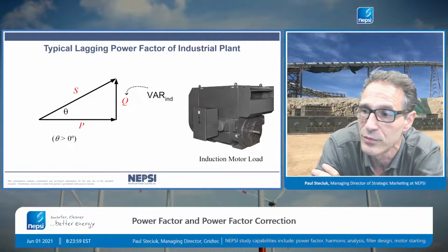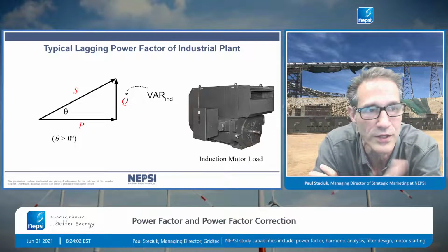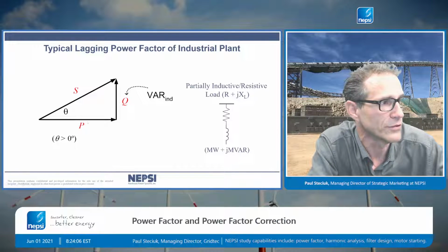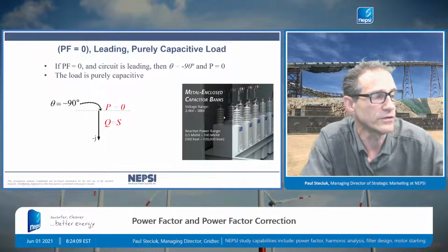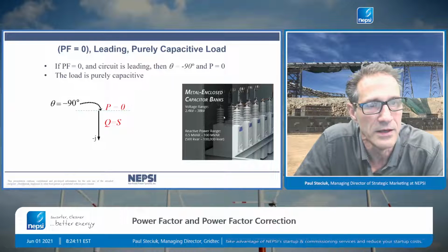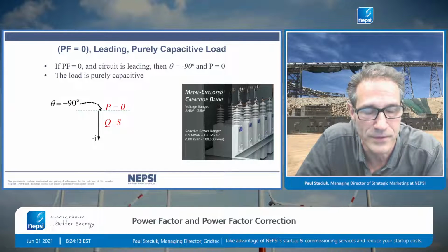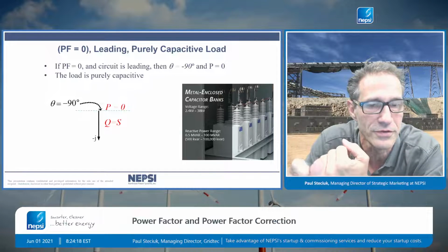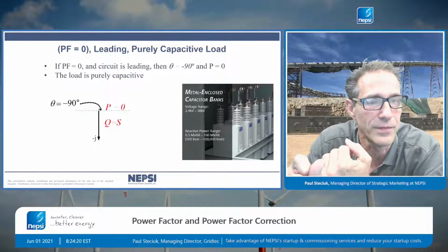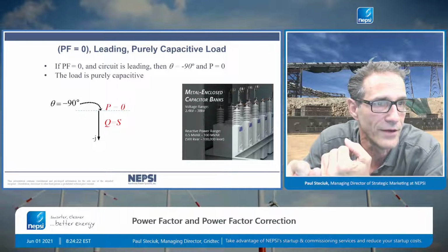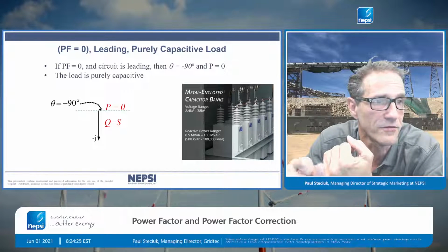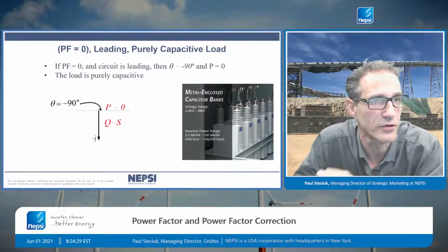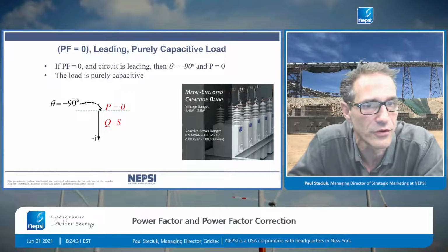Victor, what is an example of a capacitive load? Good question. The capacitive load is a capacitor bank, as we've shown here. Other examples are STATCOMs, something that also American Superconductor produces. So a STATCOM is a power electronic device that produces reactive power, but it's being put on a system for the purpose of reactive compensation, because we need to correct power factor. We're going to get into reasons why you want to correct power factor.